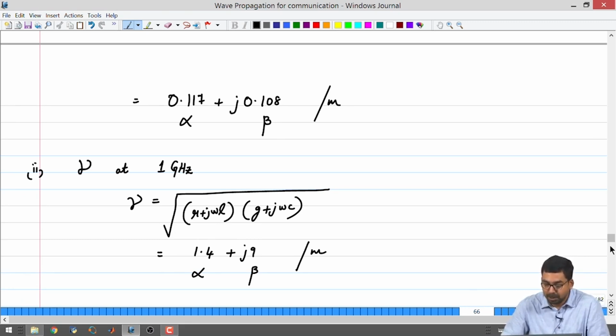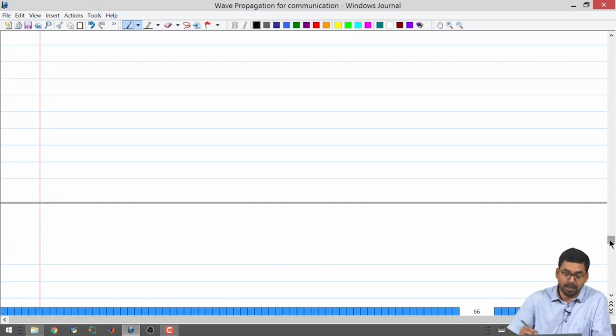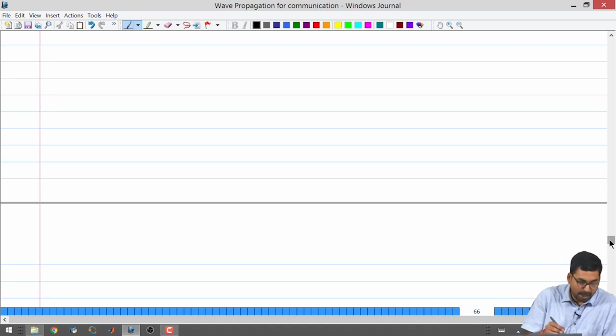But suppose you want to go to extremely high frequencies or extremely high bandwidths, then the approach of transmission lines is going to be questionable at best. We already noticed that even with some practical values, gigahertz frequency operations are already very, very tough in wired cable based transmission lines. Just to give you a feeling, we moved from 1 megahertz to 1 gigahertz. That is about a 1000 times increase in frequency, right.